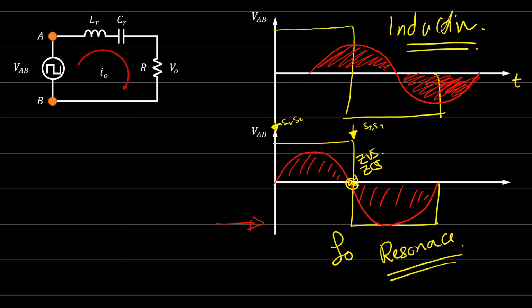So that's why we can obtain, in addition to the maximum power that can be extracted, also when we apply switching action, this occurs at soft switching. So the voltage or the current can be zero, then we apply the switching action. Okay, we send the signal at this point.